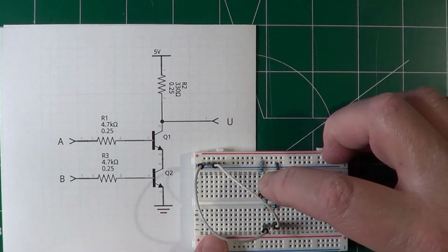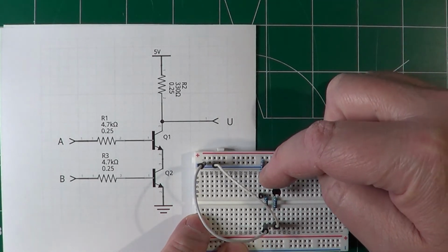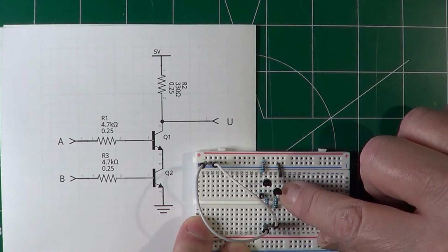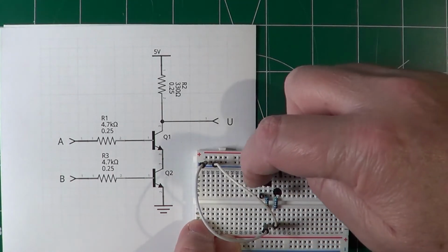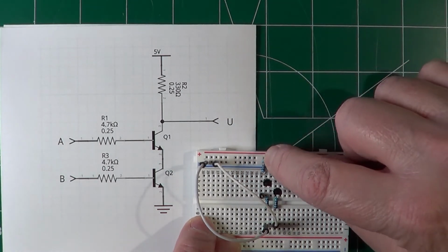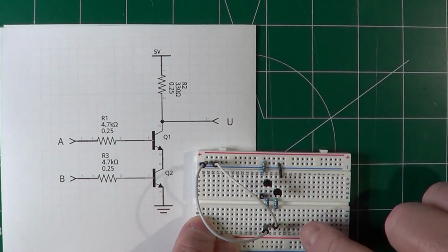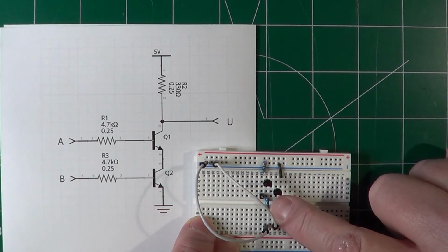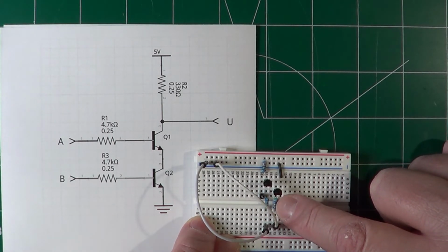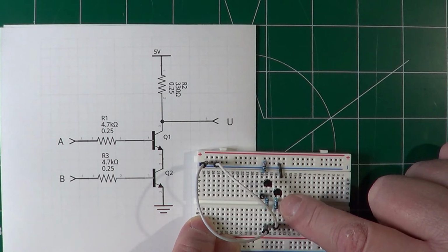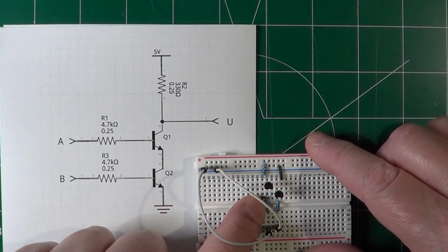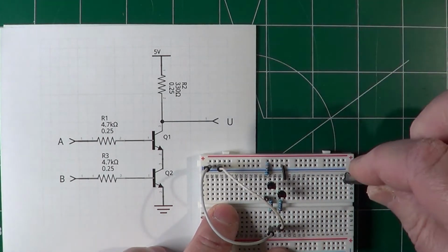You can see the two transistors here, where the emitter of the first one is connected directly to the collector of the second one. The emitter of the second transistor goes to ground, while the collector of the first transistor goes to the positive of the power supply through the 330 ohm resistor. Here are the two resistors connected to the bases of both transistors, 4.7K each, which make up the two inputs A and B, which right now are both connected to 0, the ground, through these two wires. This pin represents the output taken directly from the first collector.